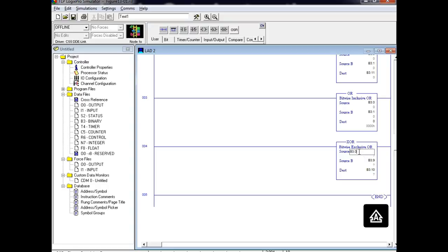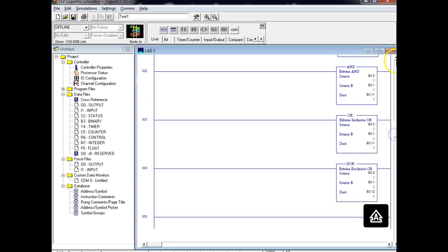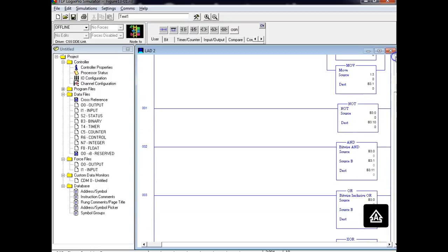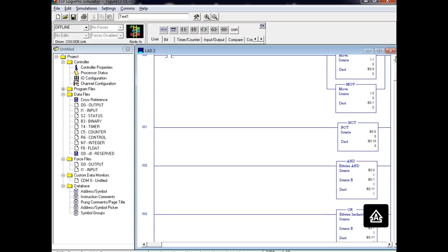What I'm trying to do is use the same numbers for everything. And so what we're doing is we're changing the output. So this will be 11. And then this right here will be B colon 12, right? You understand what I'm doing? We're using the same bits as our inputs, all except for the NOT. And that's probably my problem a while ago. When I saved it in an integer register, my NOT interpreted it as an integer, so it gave me a negative sign. That was probably my problem.